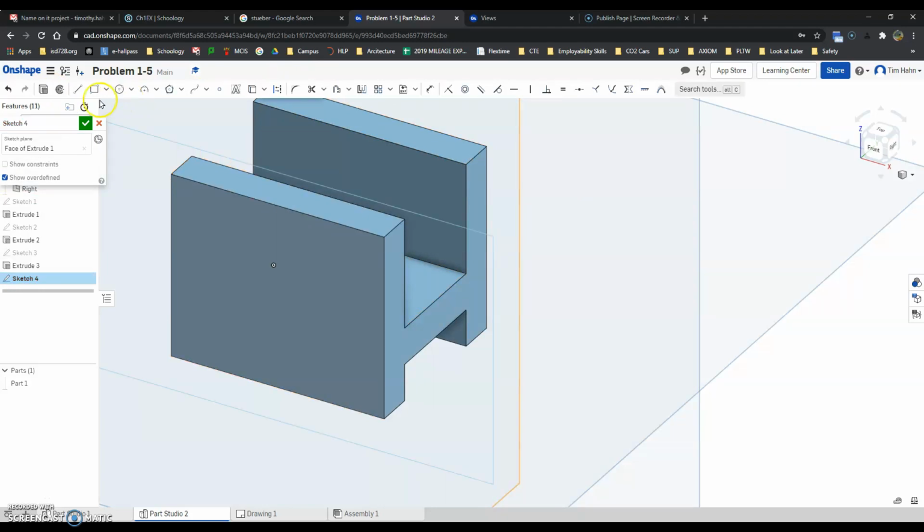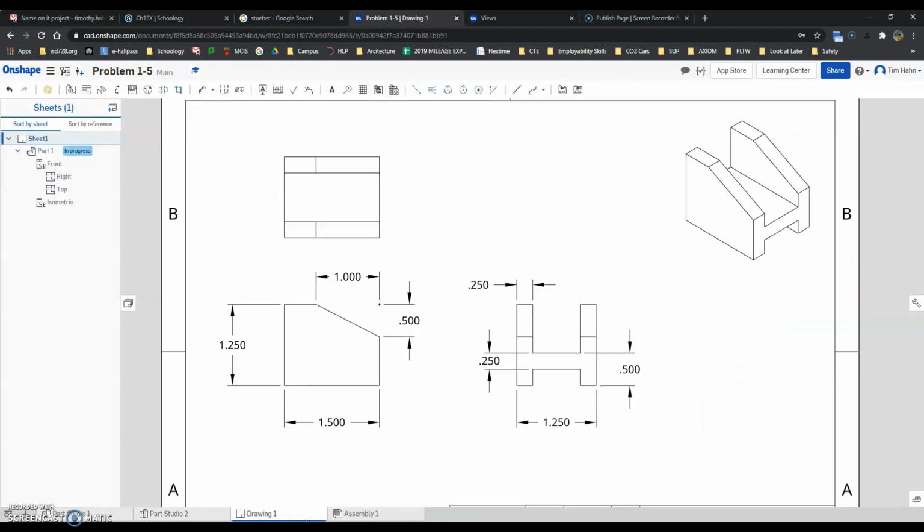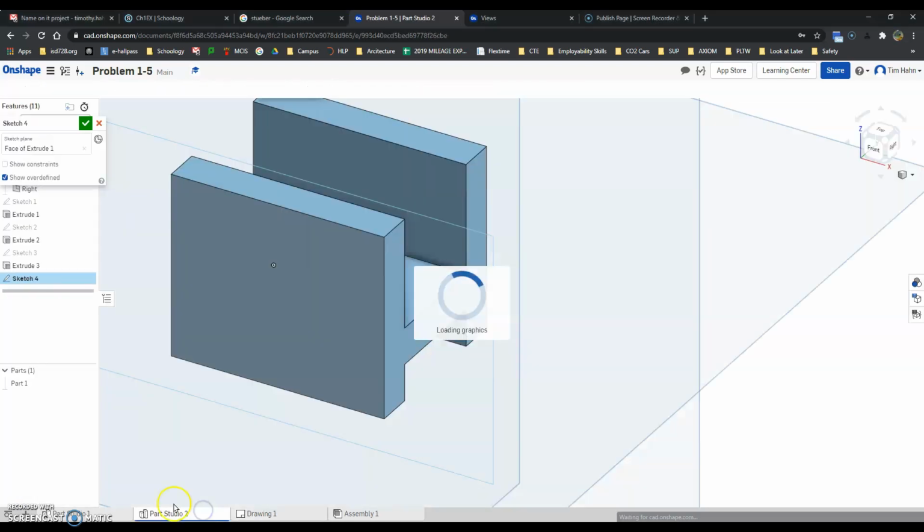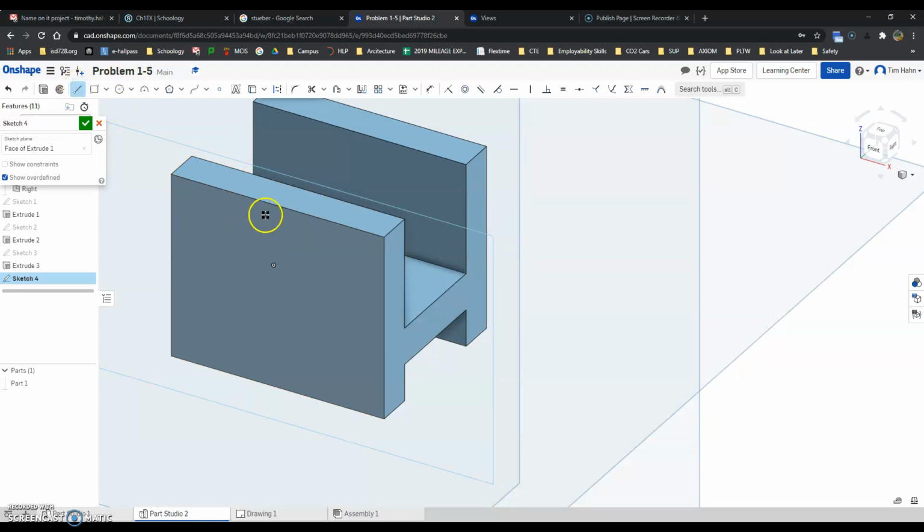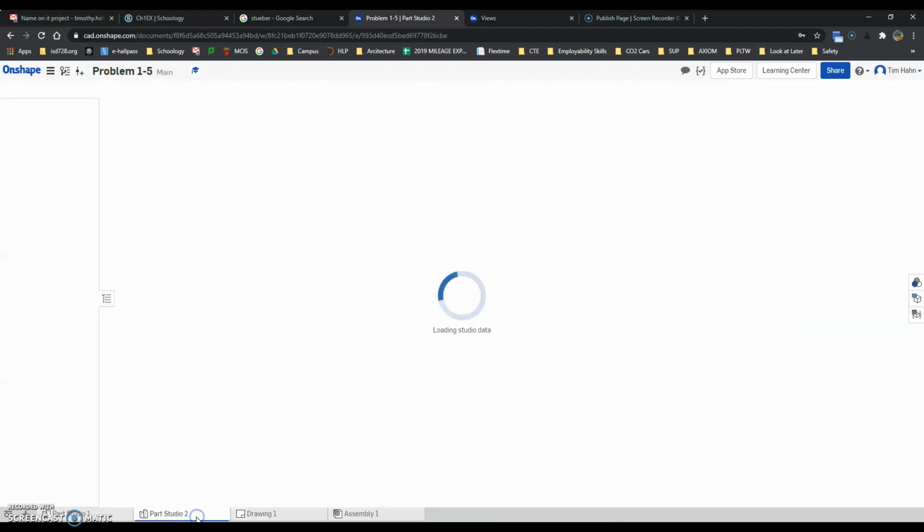Sketch. Side wall. Now we're on to, so we got our H done over here. We just got to cut our corner off. 0.5 from the top, 1 from the back edge here. So let's go over and get that done. So drawing a sketch on the side with a line, corner to corner. And then we're going to define that. Top edge to here. 0.5.